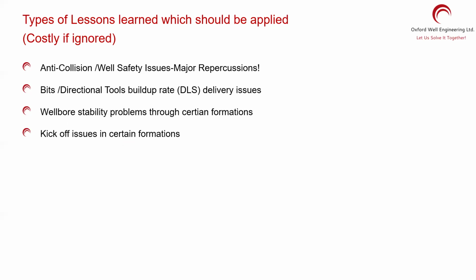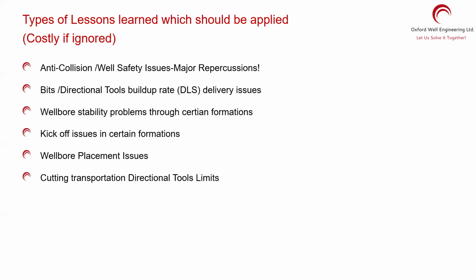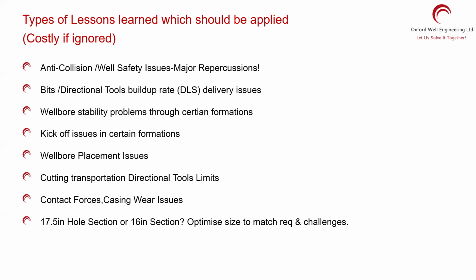Same about the kickoff point, which I mentioned. Sometimes it's difficult to kick off in certain formation. Wellbore placement: sometimes you did not place the well right. You should know what you did, why you need to improve, and what could be the solution for your next set of wells. Cutting transportation, contact forces. Contact forces and casing wear is a well integrity problem, so you want to be on top of it by learning about it.